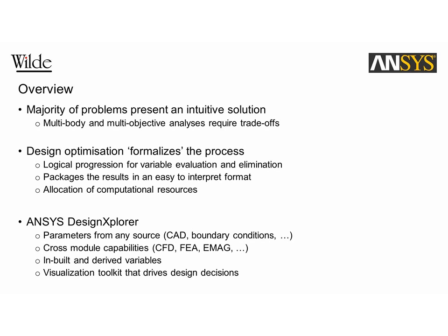We can work with inbuilt and derived variables. By inbuilt variables, I'm referring to items like thermal strain, von Mises stresses, pressures, velocities, temperatures, but also derived variables. In your industry, for example, you might have a certain variable that you care about, which is formulated on the basis of these derived variables. Thrust is a prime example, which is a function of mass flow rate and pressure and velocity. So you can optimize and parameterize thrust as a function of these basic variables.